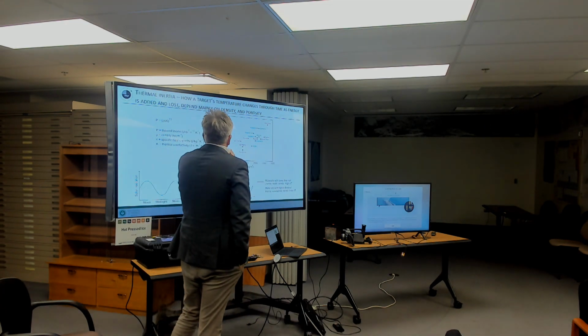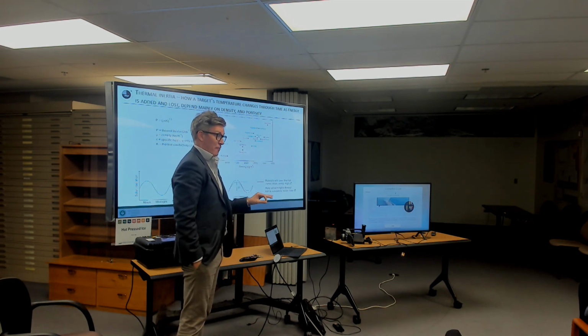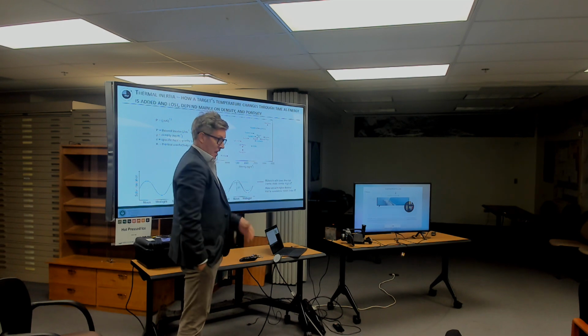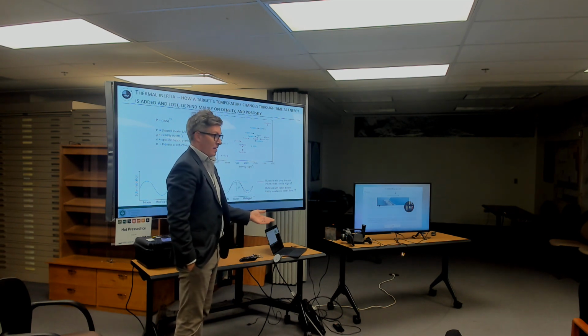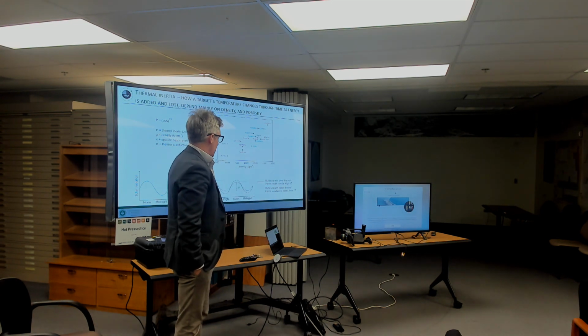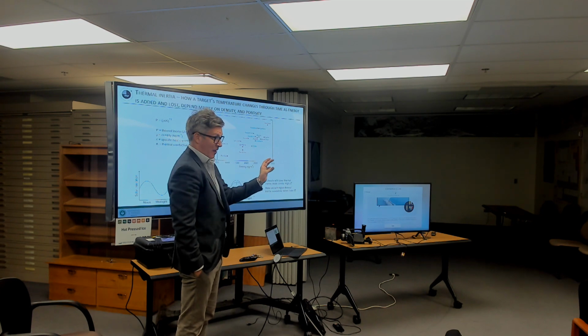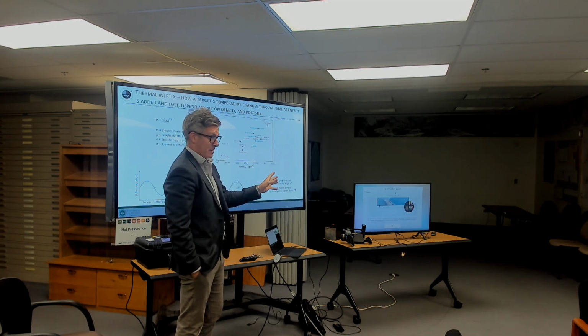So if something has a low thermal inertia, that means it has a low resistance to change, therefore it changes more. Okay? And you agree the red curve changes more. The delta T is larger. It gets hotter and it gets colder. The material with a high thermal inertia, that's dampened, right? It doesn't get quite as hot, it doesn't get quite as cold, right? Because it resists the change.